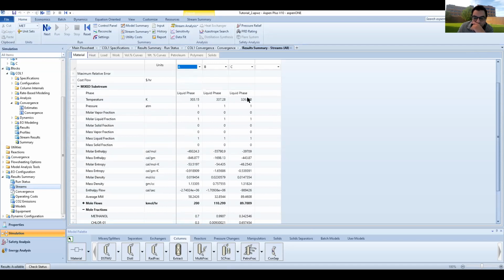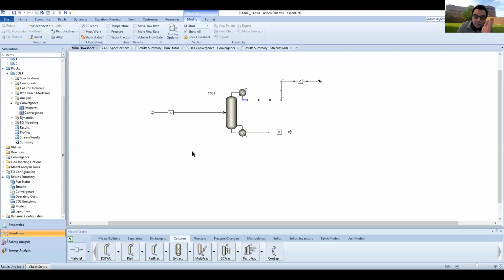We don't have a temperature, but what do they mean by the azeotrope? They're talking about this top stream. So if you recall in your tutorial, we said we're going to do a two-step separation. First step, I'm going to remove almost pure methanol. And then my mixture here at the top is at its azeotropic conditions. And then I'm going to take this azeotrope, pump it up to the other side of the thermodynamic curve, and then do another separation, right? So the temperature of this azeotrope, or the temperature of stream C,